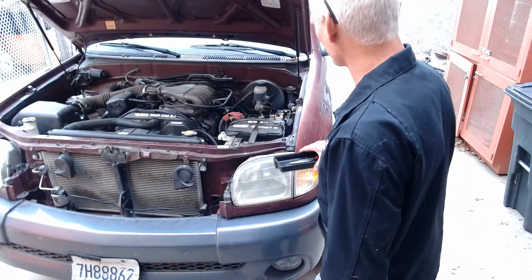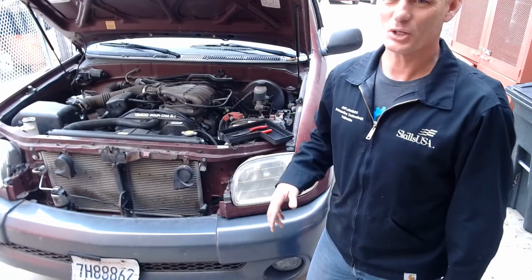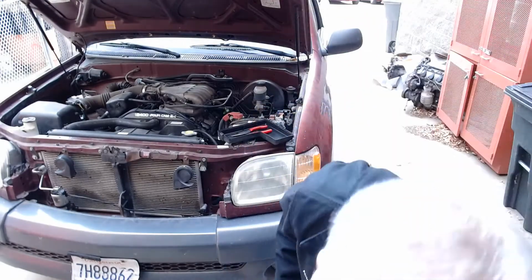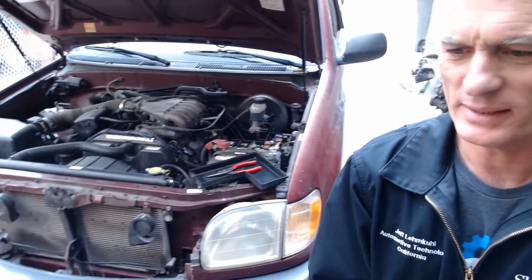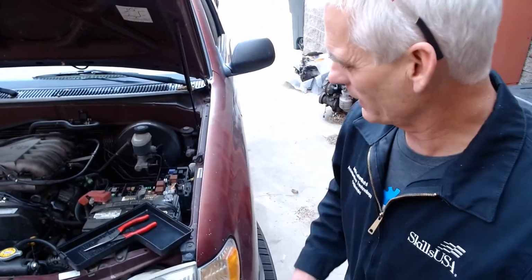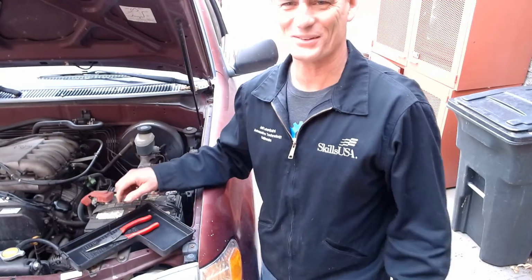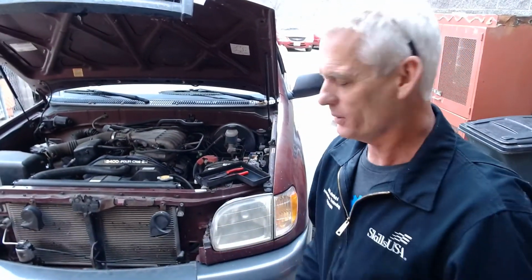Okay, so this is a really fun situation. We pulled that circuit opening relay out. Let me just pull the camera forward. And then all of a sudden it didn't want to start. So we thought, oh, okay, it's controlling cranking. Well, I put it back in. It's doing the same thing. So guess what happened? My starter motor malfunctioned during this test, which is kind of cool because it's a real live diagnosis problem. So let's do this.